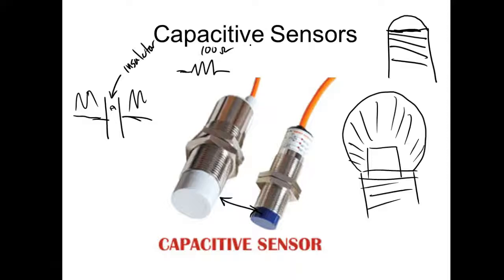If the frequency goes down, its opposition goes up. So we don't call it resistance on a capacitor, we call it reactance. And that's the name because it reacts to frequency, right? You understand? So we don't buy capacitors in ohms. Why? Because the ohm changes with frequency. Okay, y'all understand that?